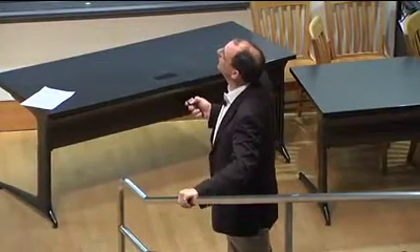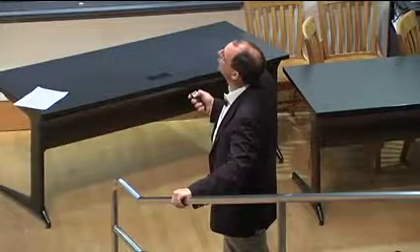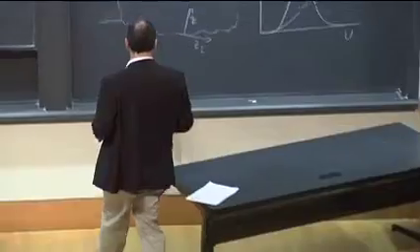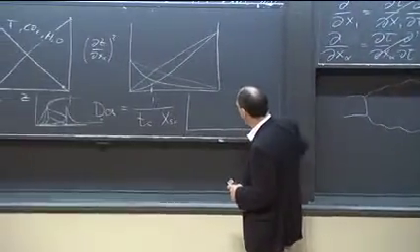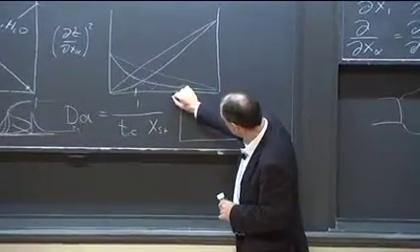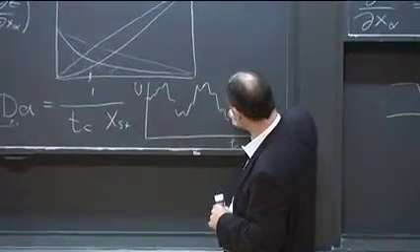decomposition. We take the local instantaneous velocity and split it up into two parts: the expectation plus the difference between the mean, or the expectation, and the real local value. We call this the fluctuation. And this is how this looks like. Let's say I measure the velocity at one point in space in a turbulent jet. This is the velocity as a function of time. Then I get something that looks like this.